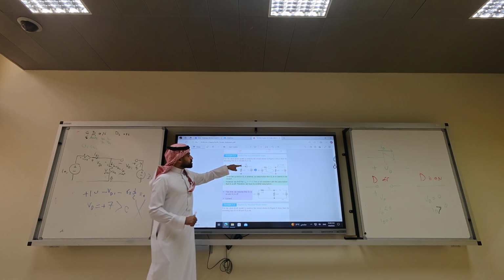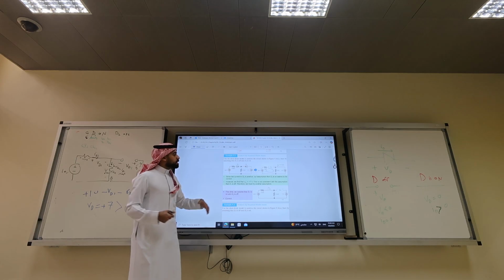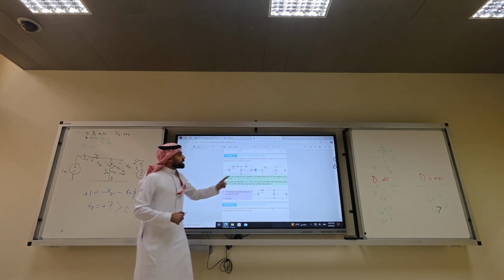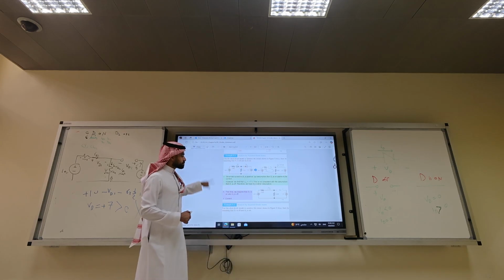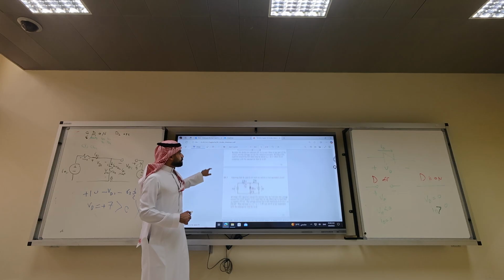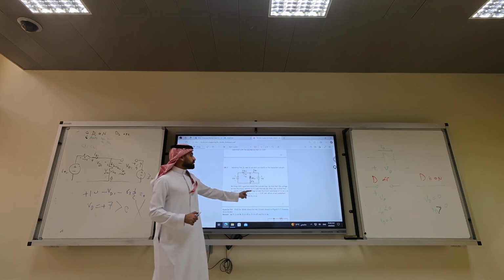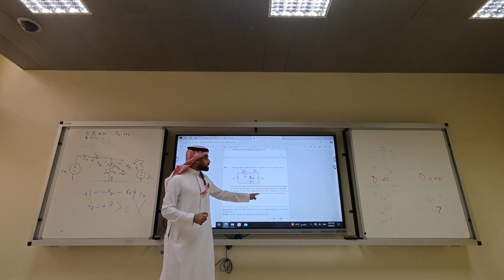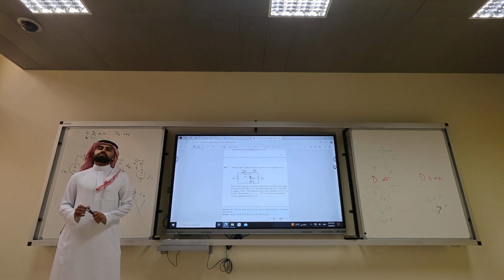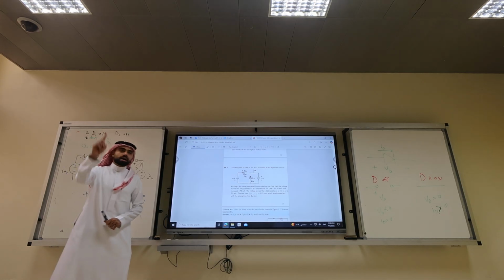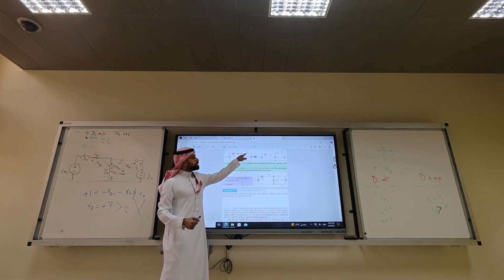If you assume both are short circuit, you have to do node voltage analysis and calculate the current, but you will notice either VD1 or VD2, one of them has a negative voltage. So for example, assume D1 and D2 are both on. We get a negative current for ID2. So the assumption is wrong. So the only true assumption is D1 is on, D2 is off.